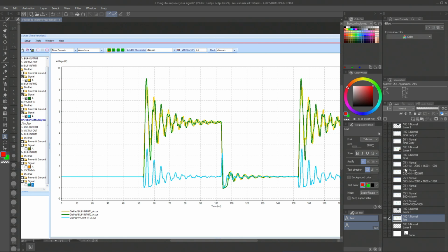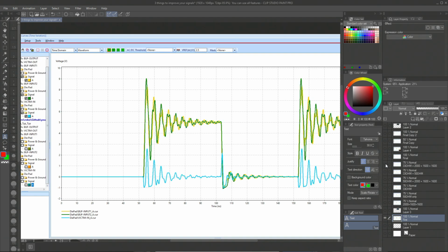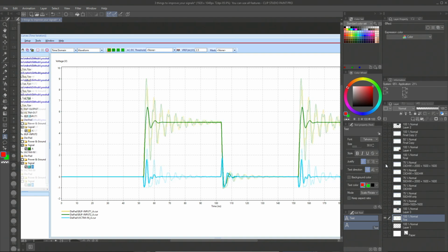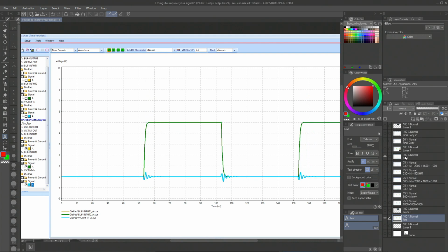And if we would use the series termination resistor and only do the length matching of the branches on the original 2-layer stack up, this is what the result would look like. And this is the final improvement when all three things are applied at once: the series termination resistor, the length matching, and also the PCB stack up.